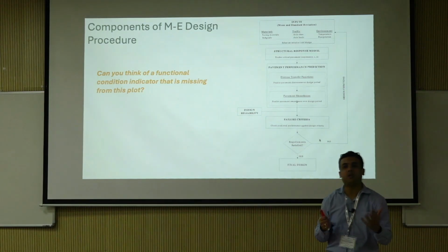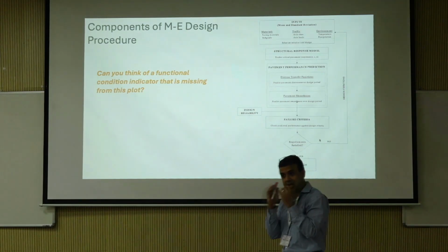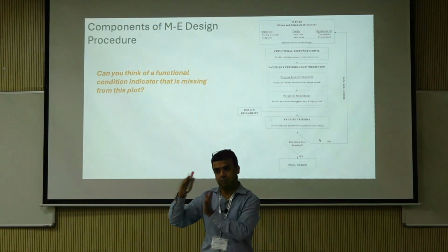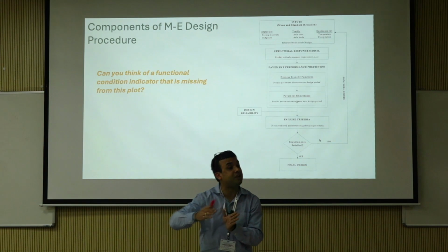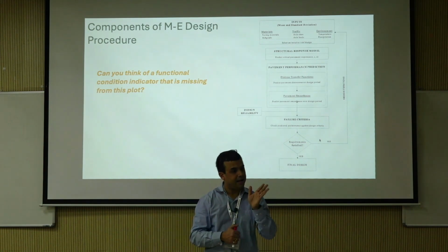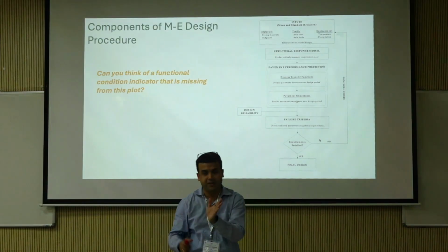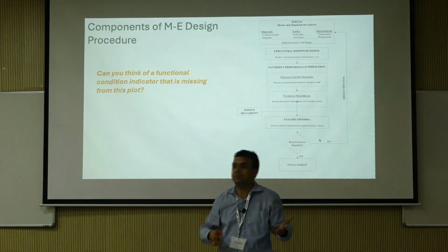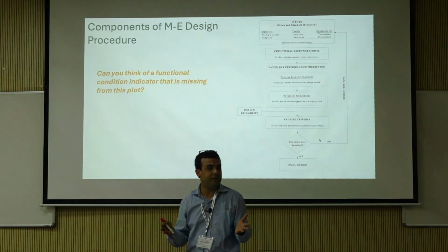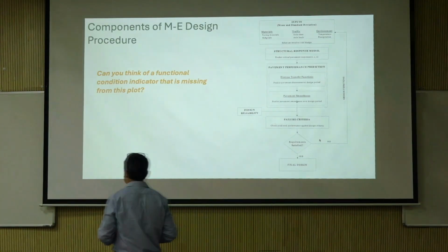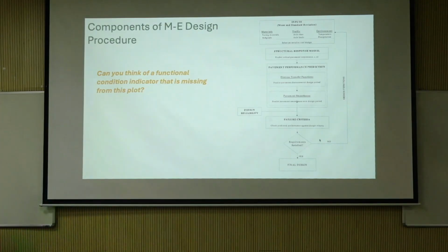That is how all the equations are developed. And the problem with local calibration is it is extremely effort intensive, money intensive, and extremely strategic. For example, a DOT will have to make a plan and go accordingly. If in the middle the DOT engineer leaves, then things fall apart, right? So that's basically the framework of mechanistic empirical pavement design.